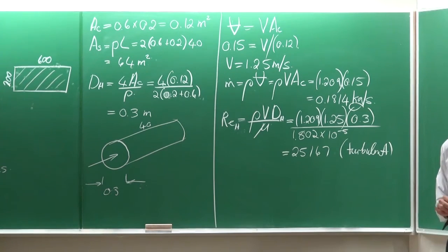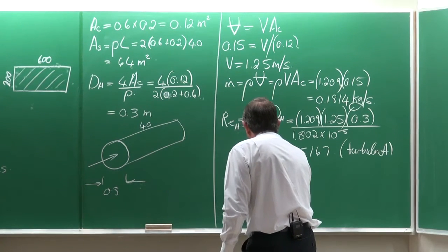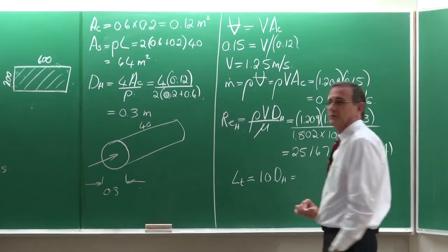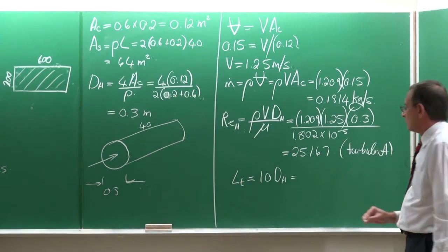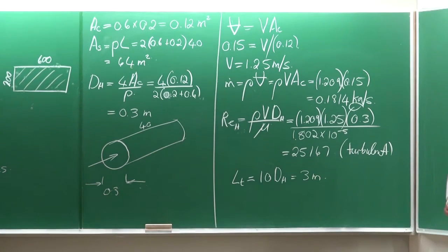Okay, turbulent flow. Therefore, because it's turbulent flow, how long will it take to be fully developed? It would be 10 times the hydraulic diameter. Okay, so it is 3 meters. 3 meters that it will take.